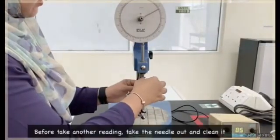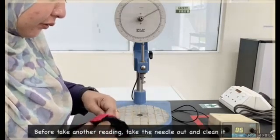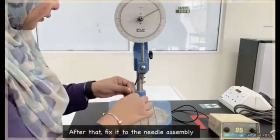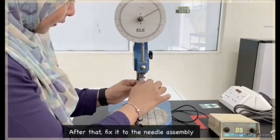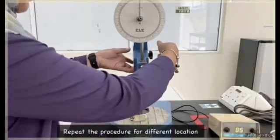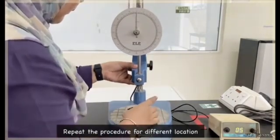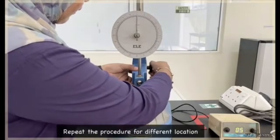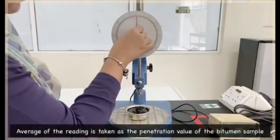Before taking another reading, take the needle out and clean it. After cleaning the needle, fix it to the needle assembly again. Repeat the procedure for different locations. The average of the readings is taken as the penetration value of the bitumen sample.